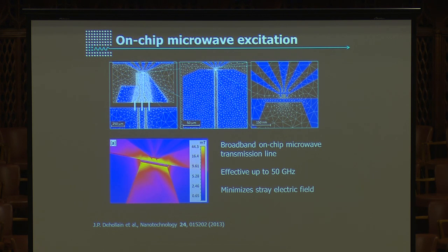And this is completely broadband, so we just use a power combiner, and we combine the tens of megahertz excitation for the nucleus with the tens of gigahertz excitation for the electron. They do go down the same line. So it's a very compact, convenient system.